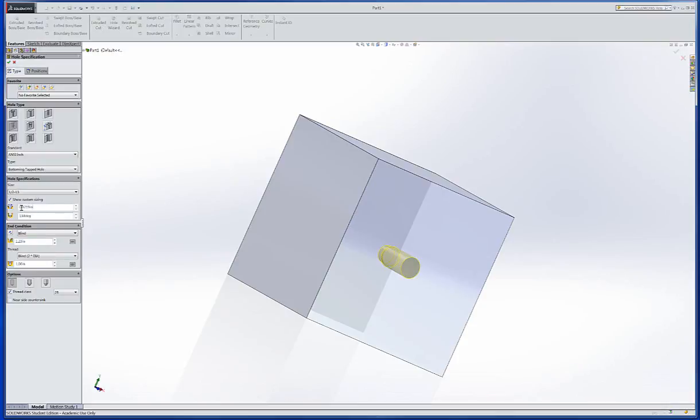Also note that this 0.4219 diameter for the actual tap drill size is how big a diameter drill bit you would have to use to drill the hole before you tapped it. That does come up by default. Leave that alone. Notice if I go in there and I change this to a 1/2-20, that number changes. So it does make a difference. This is 75% thread engagement, and that's standard. So let's just leave that alone.